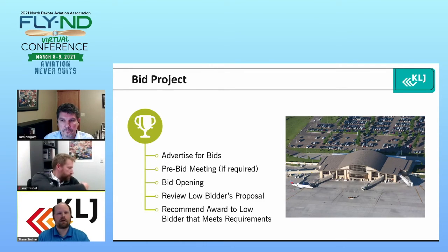Now, it's not required for all projects. Kind of goes back to the scale of the project. If it's a large project, it's encouraged. If it's a smaller project, like say a seal coat, crack seal, pavement markings, probably not going to be worthwhile to do the pre-bid meeting. And the contractors bidding on those projects are pretty specialized and have worked on airports before, so probably not worth the time and the energy for those. But for the more complex projects, especially where safety is a concern, they are a pretty good idea.